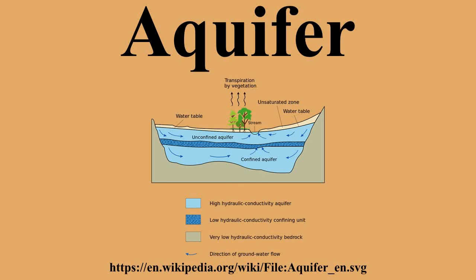The term perched refers to groundwater accumulating above a low permeability unit or strata, such as a clay layer. This term is generally used to refer to a small local area of groundwater that occurs at an elevation higher than a regionally extensive aquifer. The difference between perched and unconfined aquifers is the size.